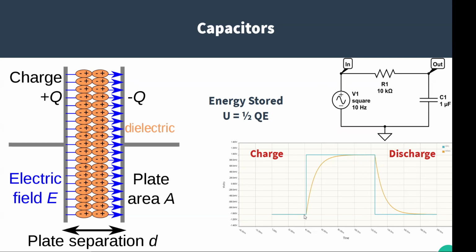When we apply a voltage to a capacitor that has no charge on it initially, like in this circuit, it's going to charge up in a time fashion because there's a series resistance. The product of these two values gives us a time constant. So it will charge up in 5 time constants to 99% of the input voltage.